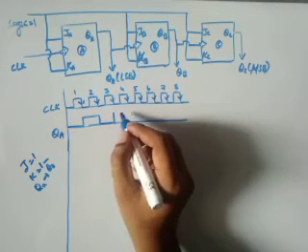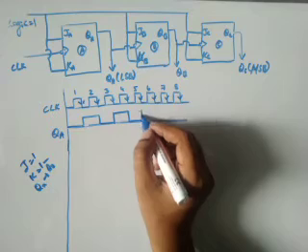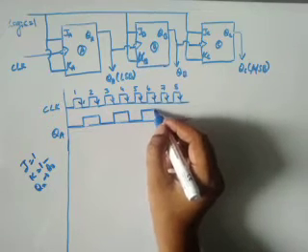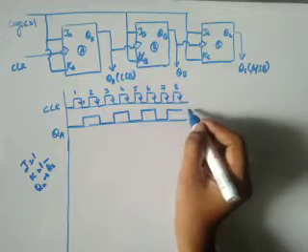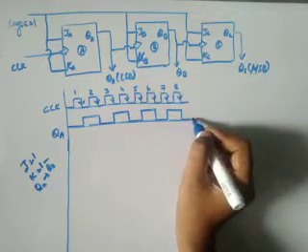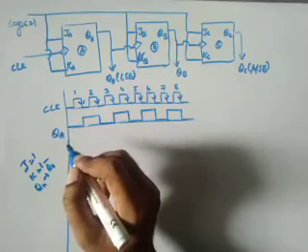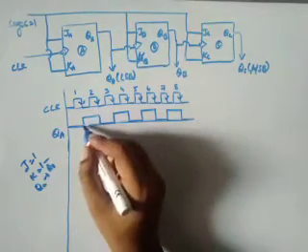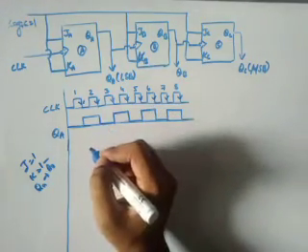Likewise it is going to repeat the cycle, changing at every negative edge. Since the input is constant with J equal to 1 and K equal to 1, it just produces the complemented value of our previous output.